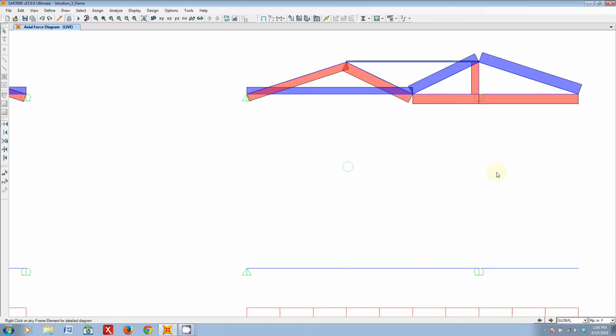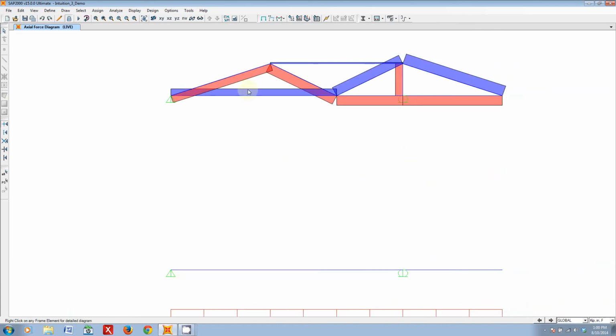Now the last example is probably the most interesting, I think, where basically we have our beam, remember, and then we went up to positive moment, dropped down to negative moment, and then went up to the end with 0. And you can kind of see how we follow the top chords in compression, and as they come down and they switch at that region where there's 0 moment, now it switches. So the top chords in compression, now the bottom chords are in compression, and the same thing with the tension coming up, it transitions.